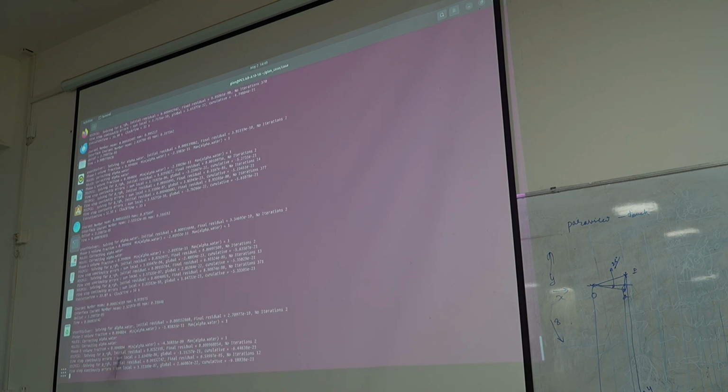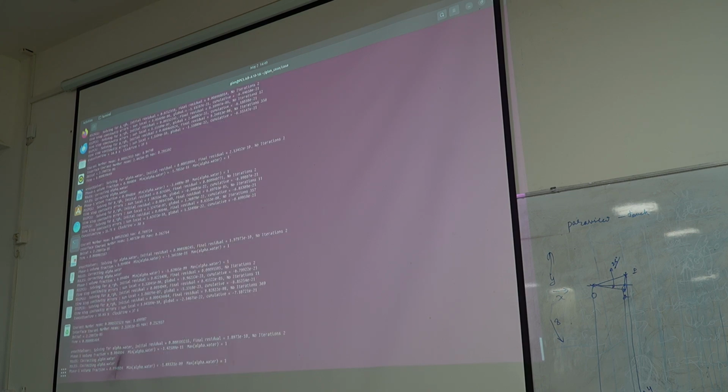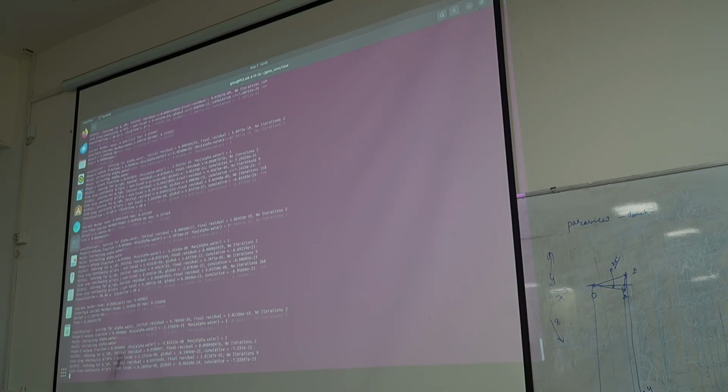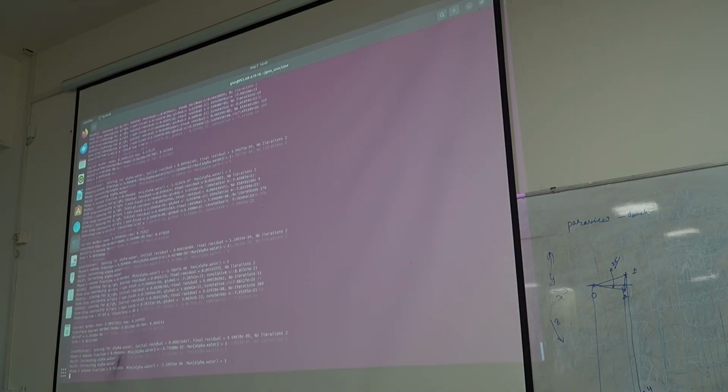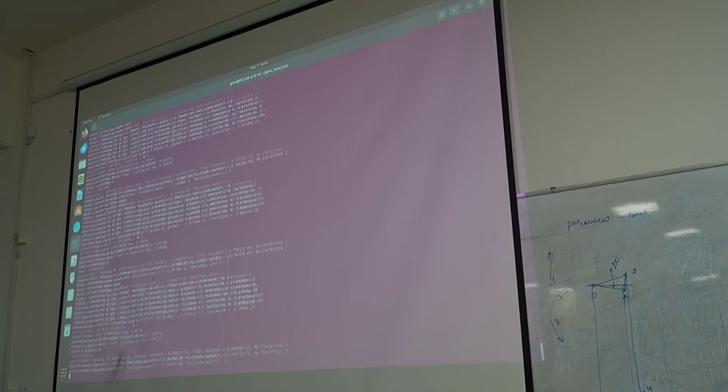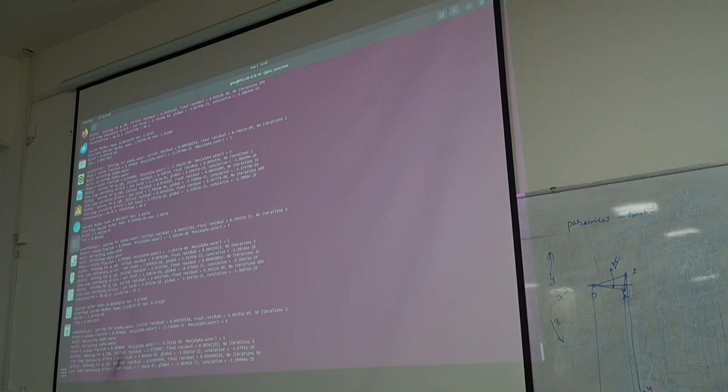And so is adaptive recommended for 2D, or is it not for 2D? No, it's not for 2D. It's for 3D. For 2D we can go to the maximum refinement; there is no need for adaptive in 2D. In OpenFOAM it is sometimes recommended, but I think in OpenFOAM it is not there for 2D cases. So the code is only for 3D.